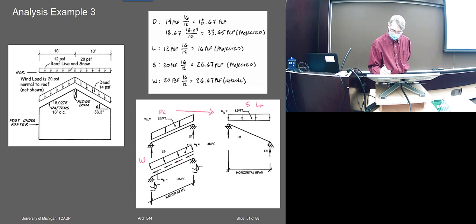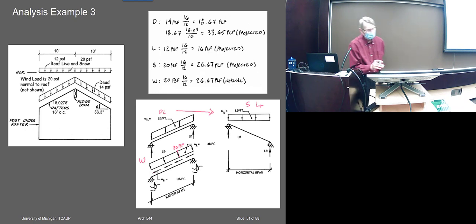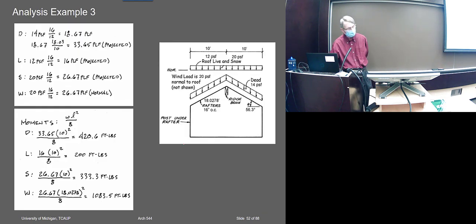I don't think it has the horizontal component, not in this case, because the wind is coming in normal to the surface. So this is the wind I've already gotten, that 20 PSF. Okay, so we've got all those, and now we can calculate the moments.